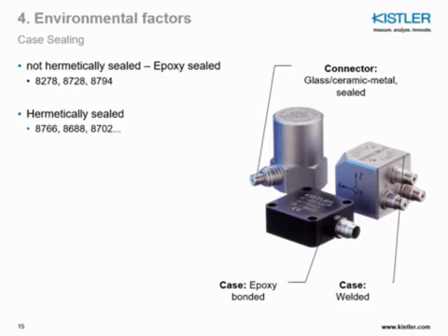In some cases, we have very harsh environments that could lead to dust, or that could lead to some steam or some water spray and so on. It's very important to understand what is the case sealing of the sensor, but also what is the tightness, IP grade, between the sensor and the cable.